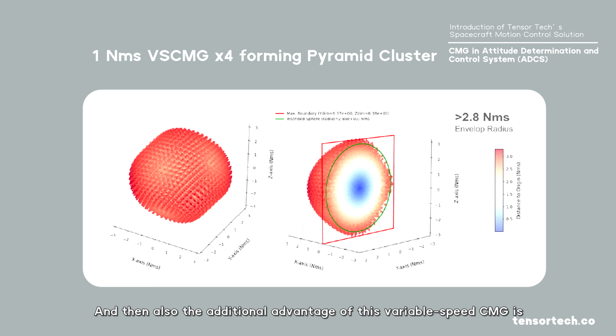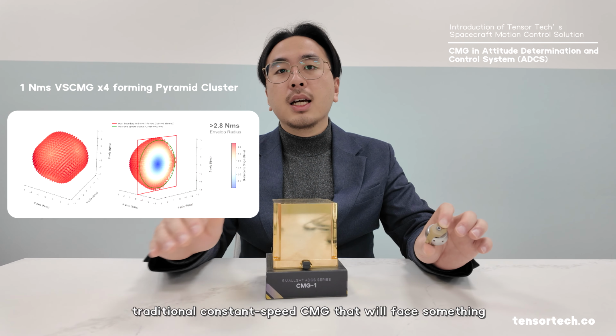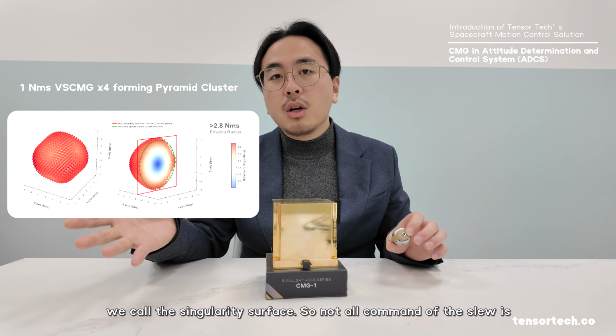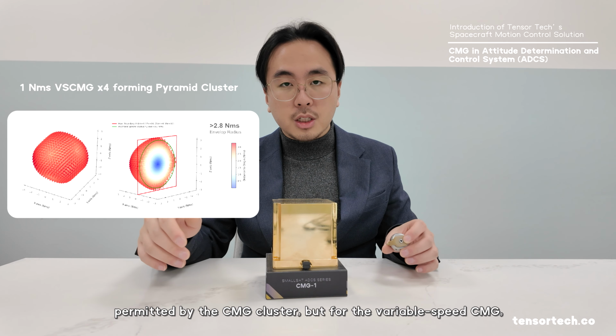And then the additional advantage of these variable speed CMGs is that they come with a singularity-free characteristic, unlike the traditional constant speed CMG that faces what we call singularity surfaces. So not all slew commands are permitted by the CMG cluster.